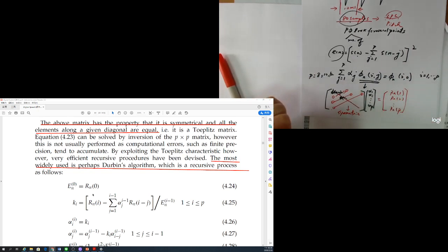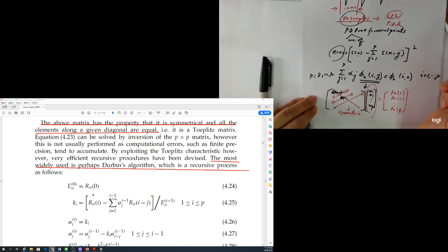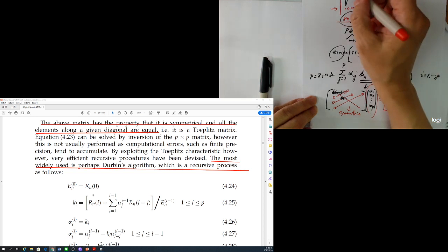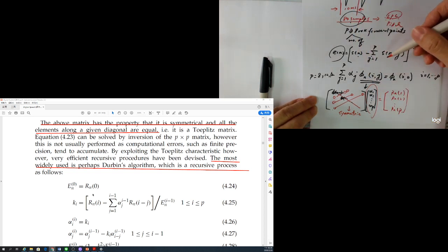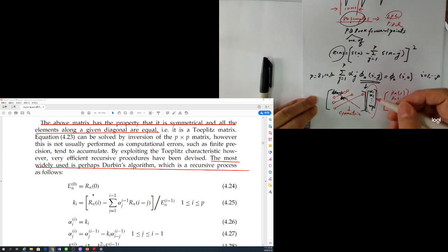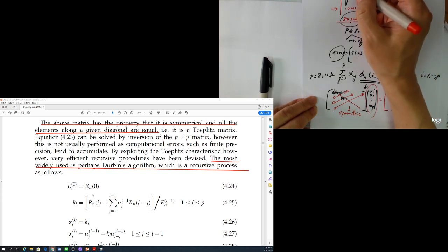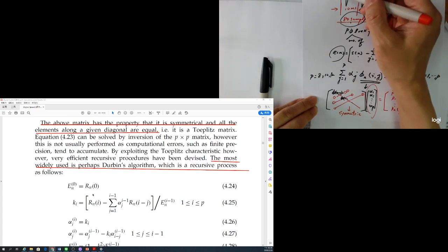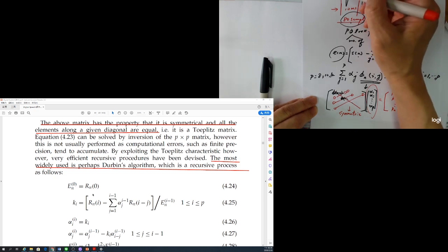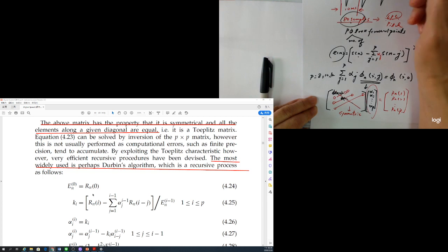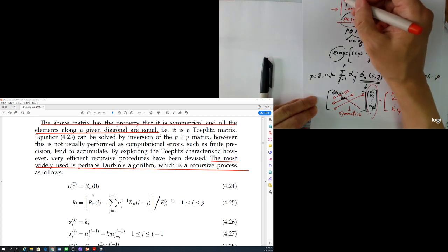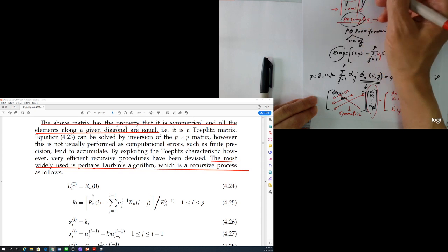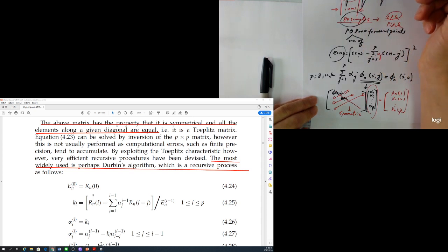Based on these coefficients, if each point uses them to do the linear combination, the total loss will be minimized. So the main idea is to find, inside the speech frame, what kind of coefficients can do a good prediction.